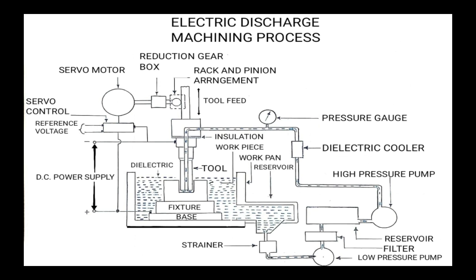When power is switched off, current drops, no further heat is generated, and the discharge column collapses. A portion of molten metal evaporates explosively or is ejected away from the electrode surface. With the sudden drop in temperature, the remaining molten and vaporized metal solidifies. A tiny crater is thus generated at the surface. The residual debris is flushed away along with the products of decomposition of the dielectric fluid.